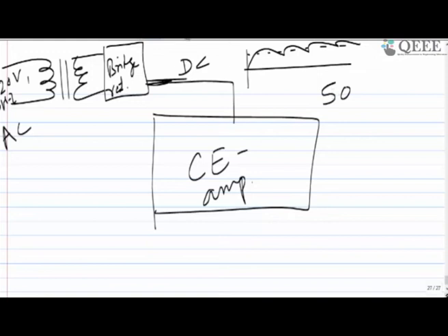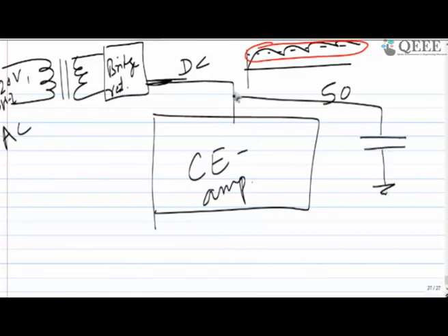So if you want to solve this problem, I don't want this one. First of all, look, this is not stable. It has to always be the same voltage which is applied to my common emitter amplifier. So what I can do, I can apply a big capacitor. The role of this capacitor is that it can only allow AC. So all the pulsating DC or the AC waveform which is at 50 hertz will go to ground, but this will not allow any DC. DC will not go here, but it will be applied only to this circuit.